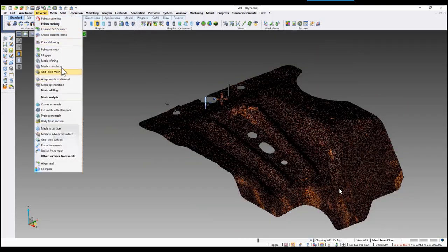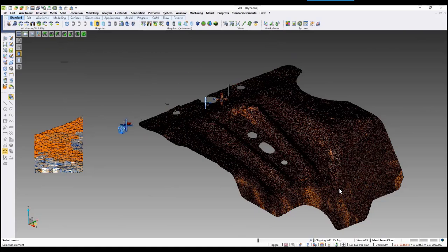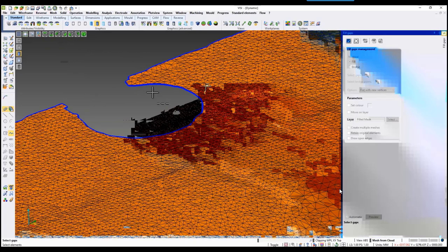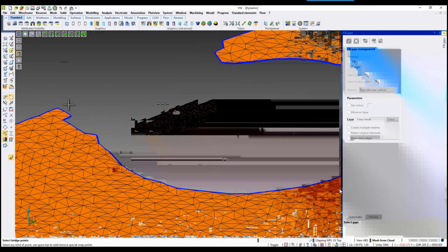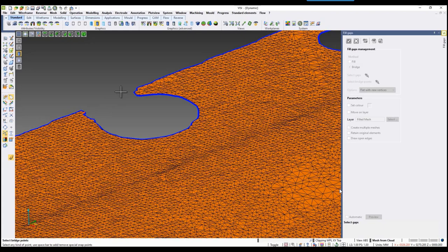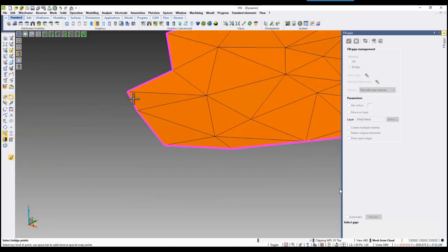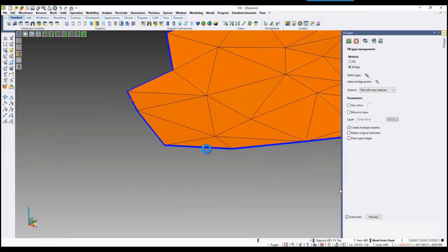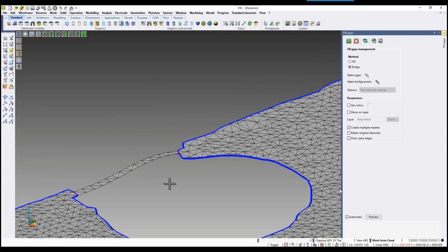So you can see how we have a couple of outer mesh areas. So we go into this meshed area, you can select it. You can see how we can create a bridged mesh. So let's just say picking a couple of points. So we pick a point there, pick a point there. And what that's going to do is that's going to create a bridged mesh to be able to fill that hole in. So as you can see, we have that bridged mesh in here.